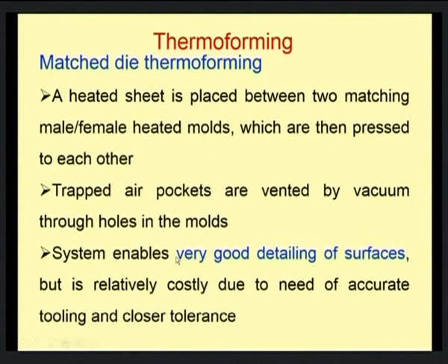Now, if you look into the advantage, the system enables very good detailing of surfaces, because once you prepare a matching mold, a male female mold, one can go for a more detailed surface finish, but it is relatively costly due to the need for accurate tooling and also close tolerance.